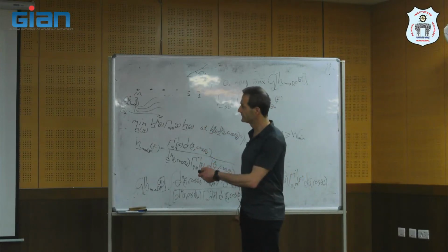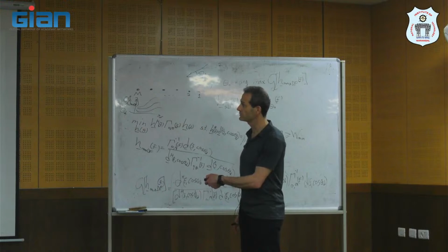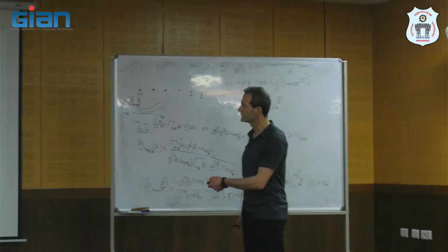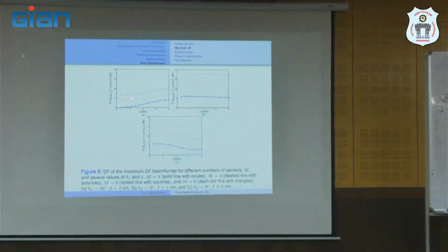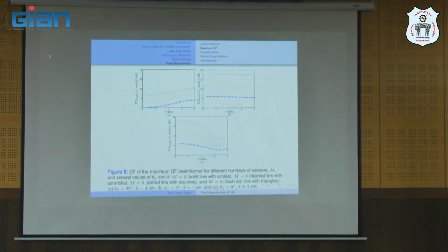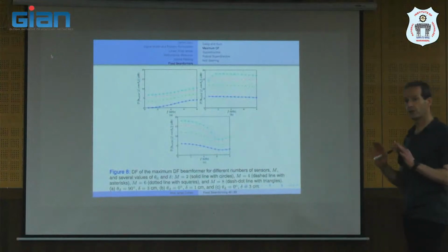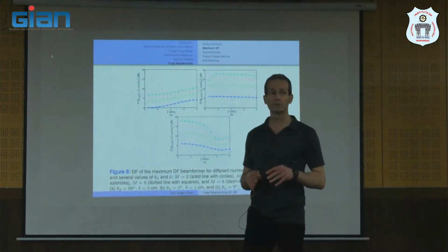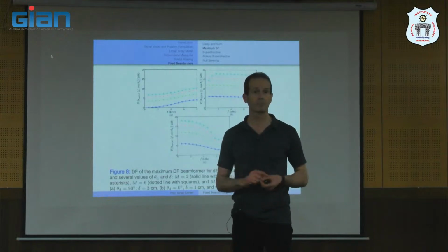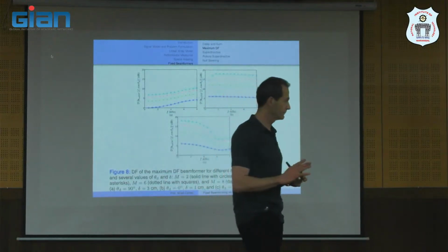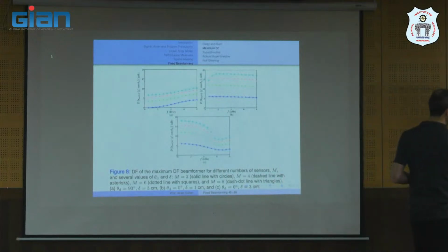But it's okay, because it's a trade-off. If we want to increase the white noise gain, especially in the low frequency, it means that the directivity factor in this frequency will be lower, because we added an additional constraint. This is the way to deal with robust optimization problems. So you can do that with any problem, okay? So how do we solve this problem?